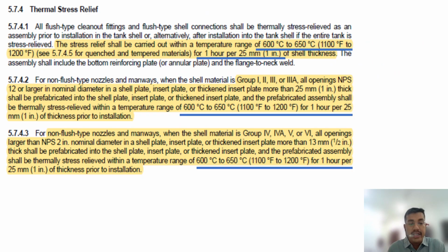Thermal stress relief is also required sometimes, if it is needed. Again, it is the call of the purchaser. So what are the stress relief requirements? The temperature range is between 600 and 650, and 1 hour per 1 inch of shell thickness is required.